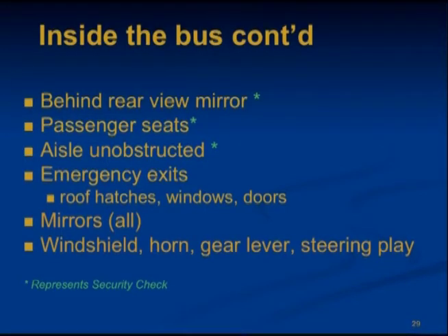Make sure that your horn works. Make sure that the gear lever moves freely. Remember that the bus will only start in neutral. Make sure to check your steering play on a non-power steering bus. Check for excessive play, turning the steering wheel back and forth.